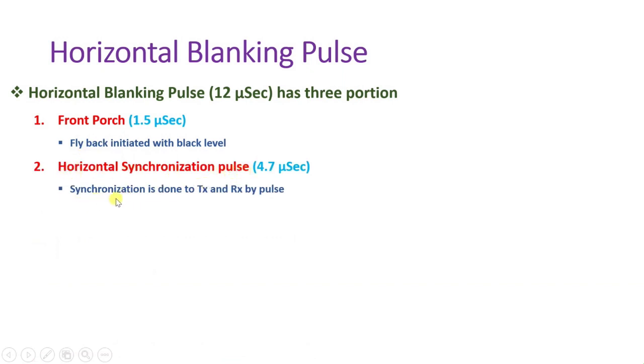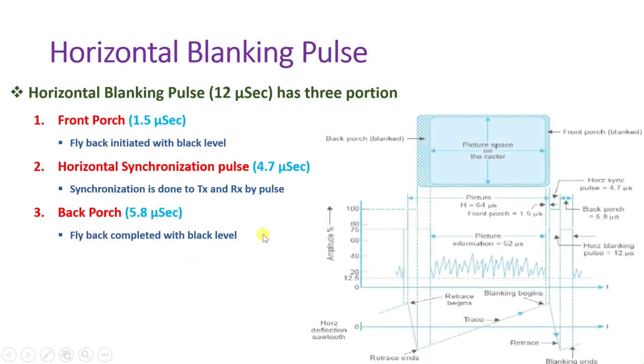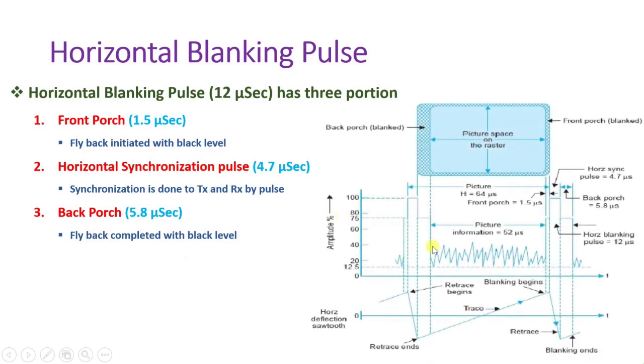Just before retracing, when the scanning beam completes its trace to the right, the blanking level of the front porch will cause the right edge to turn black, with a small amount of each line blanked out in this way. This black bar to the right can be thought of as a reproduction of the front porch portion of the horizontal blanking.